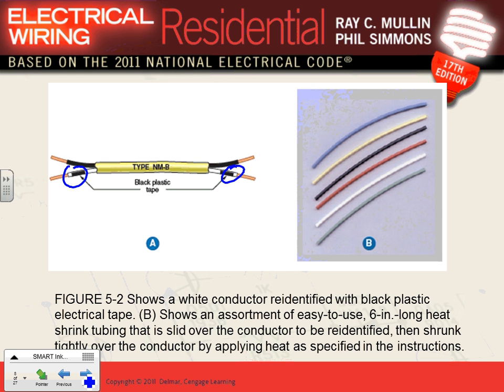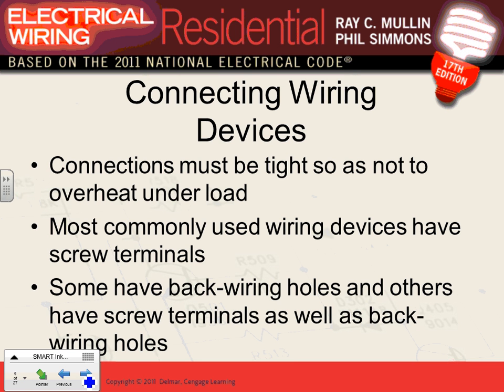For the most part, because now you have to bring a neutral to the switch if you're wiring with cable. And guess what? If you're wiring with conduits like here, you can't re-identify anyway. There's no re-identification. So if this was an MC cable coming here, an MC cable coming here, I can't re-identify the neutral. Everybody understand now why? Because they have to have a neutral here in this box. Any comments, guys, about re-identifying the neutral as supply for the switch? Okay, so that's a couple of things about re-identification.